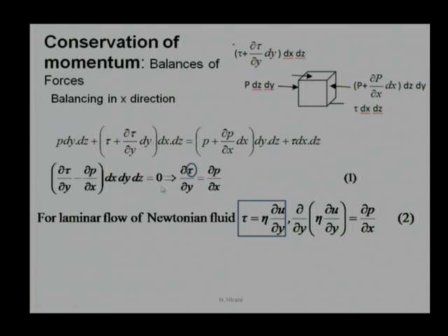If I use this equation, equation number 1, we can get pressure in terms of velocity and viscosity. If viscosity is 0, we know the pressure will not be generated. Or if there is no relative velocity or no velocity gradient, then again there will be 0 pressure. So that is why for hydrodynamic action we require both. We require viscosity, we require velocity gradient, we require relative velocity. If there is a relative velocity, velocity gradient will come.